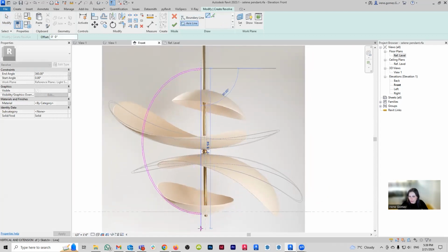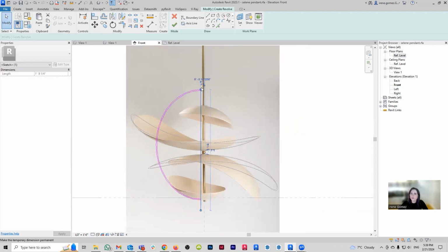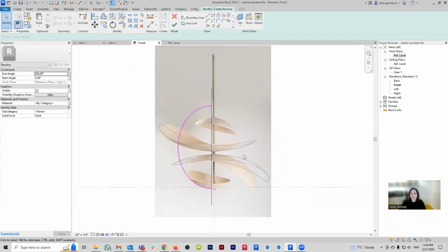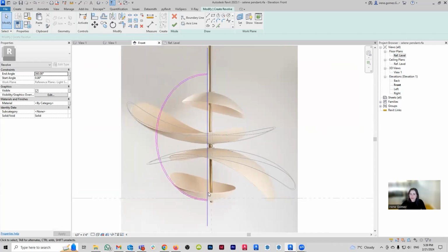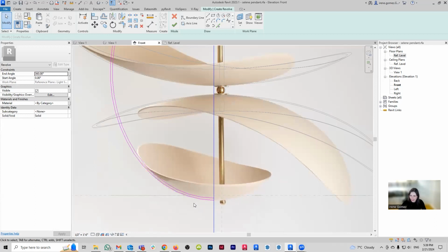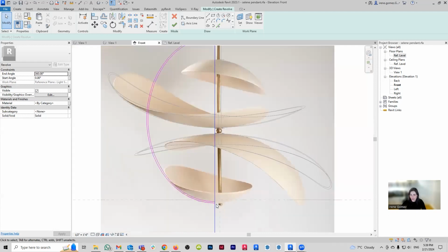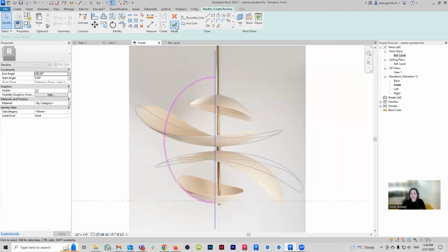So one thing that I'm not entirely sure is coming through, but working with circles and ellipses and working with very small dimensions tends to be very finicky. Revit does not want to. So if that happens to you, just don't get frustrated and just pivot. For example, here, I cannot make it 2 millimeters. Fine, I will increase the size until you do the thing that I want you to do. There is no point in me fighting Revit because Revit is always going to win. So I'm going to finish here.